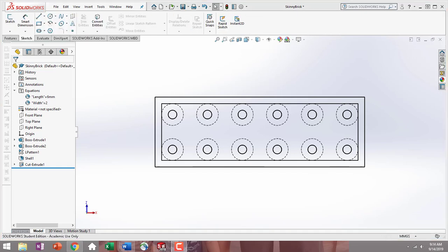Okay, so now that you can see the bottom edge of all your parts, I'm on step 7. It says we're going to create a sketch on the underside, so that's the face we're on now. We're going to convert entities and bring the 4 outer circular edges of our bosses or knobs into our sketch. That's why we're using the hidden lines display style, because now you can see the outside edges of those knobs, where you need to bring 4 of them into this new sketch.